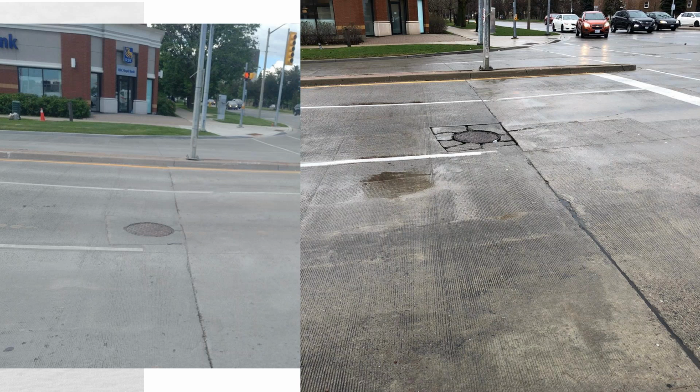So what we're going to do is we're going to go in. We spoke to the depot about ways that we can fix this, and they actually don't need that maintenance hole. So we're going to go in and pull up the area around the maintenance hole and the slab adjacent to it, because it now has a crack that's transferred through it. We're going to lower that maintenance hole back down to subgrade and then rebuild our granulars and concrete on top of that. So that's what we're looking at doing now, either this year or next.